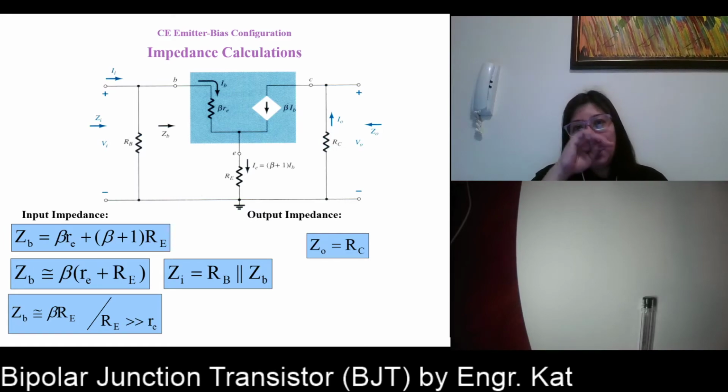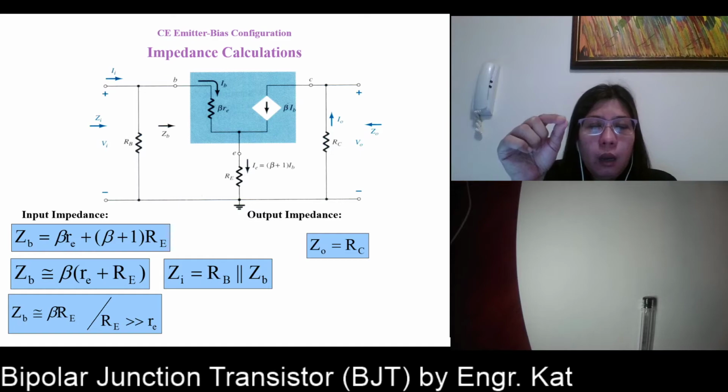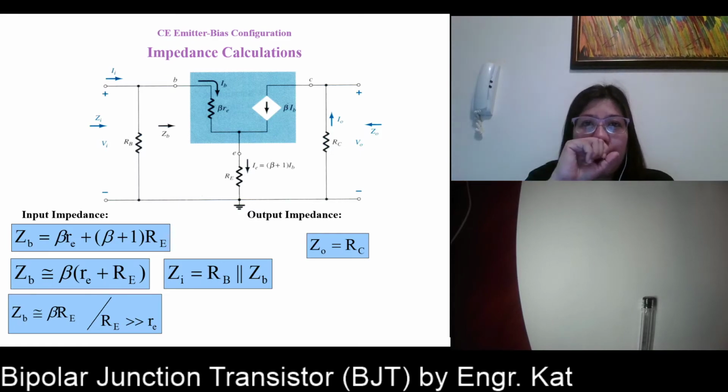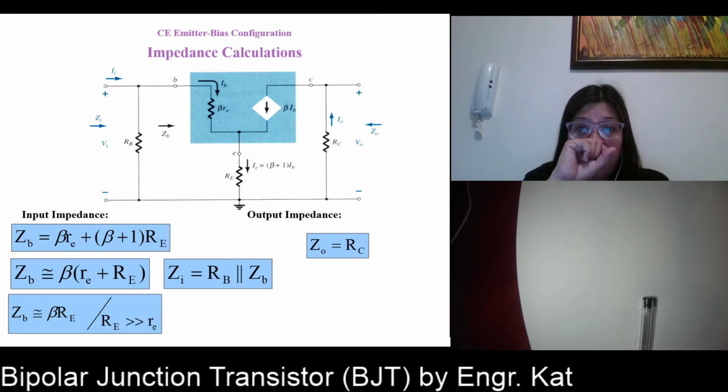Okay, so those with smaller cap, lower cap letters, they are your AC parameters. You don't borrow them from the laboratory and then place them in your circuit. Usually it is within the transistor itself. Okay, so at the output side, since we are opening your current here, no effect whatsoever. Therefore, for the output impedance, it is just equal to your RC. So the only impedance that is shown at the output is your RC.